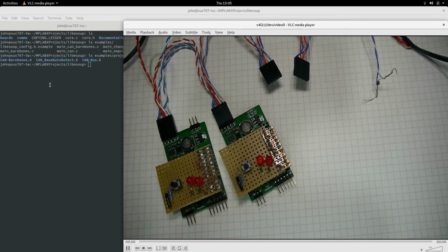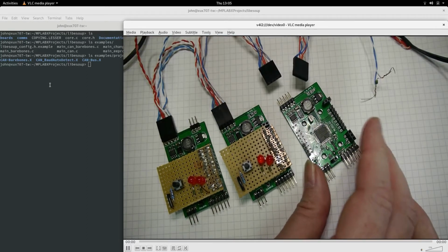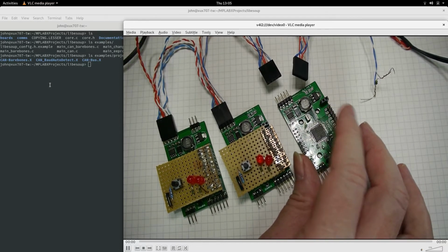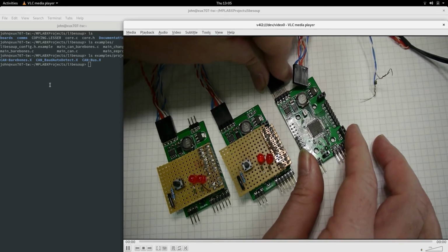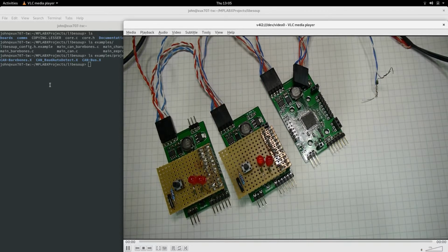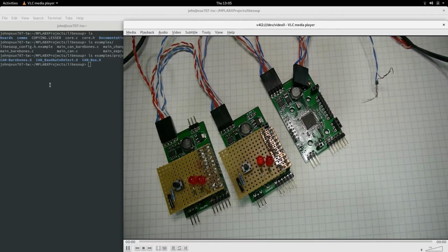If anybody else transmits, they'll both receive it. You don't receive what you transmit yourself. That would be loopback mode, and that's only used for test. So this node is a very simple node, no expansion, but I've got a 1-second timer, and all this node does is send out a 777 frame. So in this case, he's sending out 777 and both nodes are reacting.